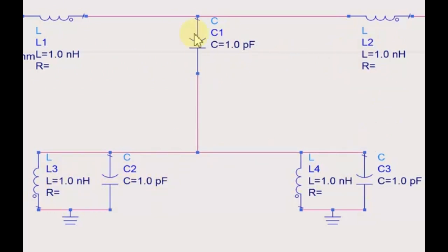We are not strict about only this circuit. If you want to make a different kind of circuit according to your logic, like placing two inductors and two capacitors in series for a split ring resonator, this circuit would also be good, there is no problem. The only thing is that when you optimize or tune the values of inductor and capacitor, you will find some different values.